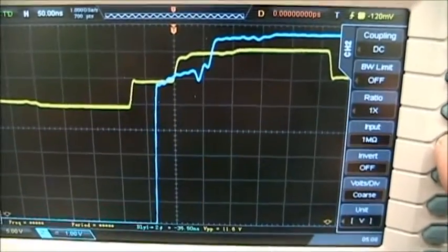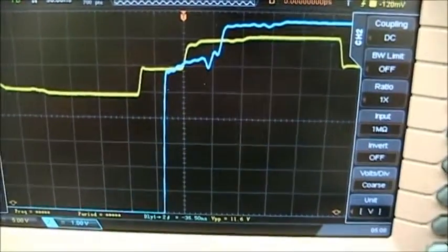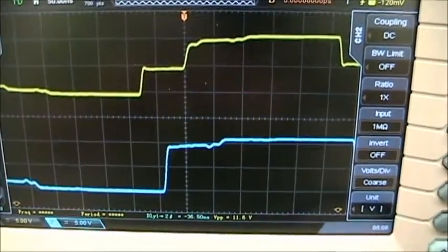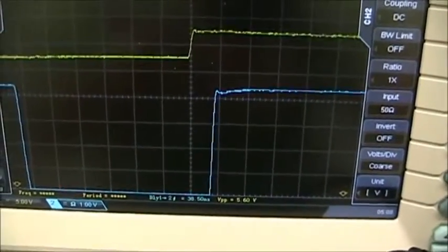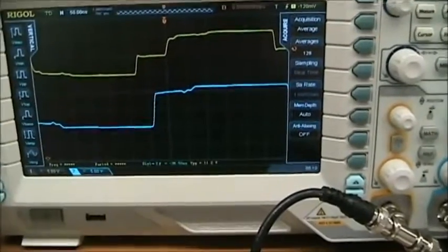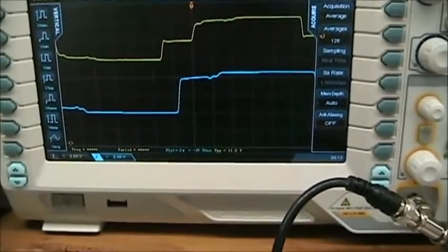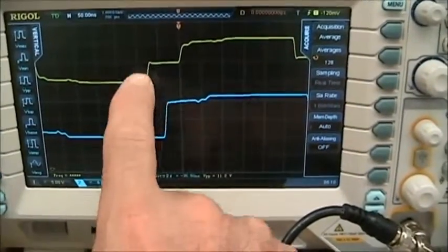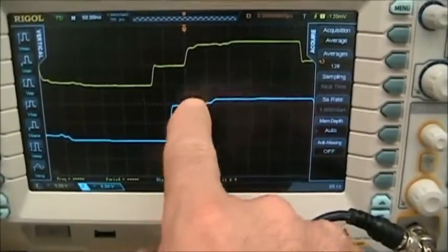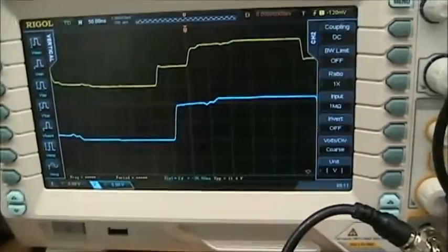So this is with the reflected value, and the other is with the 50 ohm match impedance. So record this waveform to an image so you can download it and put it in your report, recording both the time delay and the change in voltages.